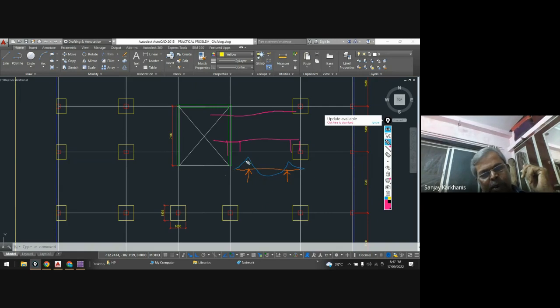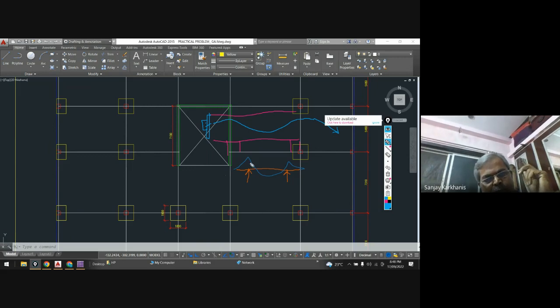And I know that in bending, here it will be tension. Here it will be tension. And here it will be tension. So I will have a cable, something like this. So this is my cable, and then this cable is clamped over here with some clamping arrangement, and then it is stressed with the calculation.